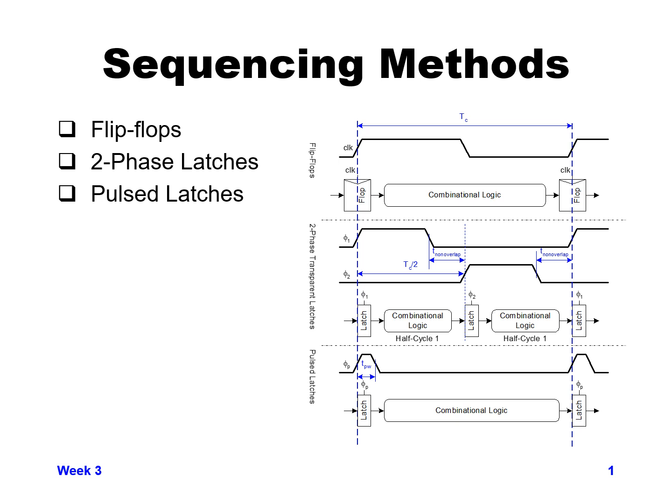When clock goes high, the latch on the flop on the left will capture a new value. That new value will go into our combinational logic, and that combinational logic could take maybe half of the clock cycle, or it could take 80–90% of the clock cycle, but we need to make sure that it takes less than a full clock cycle to get a stable value at the input to the following flop on the right.